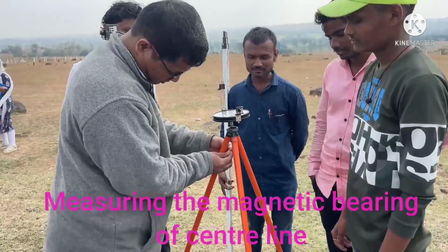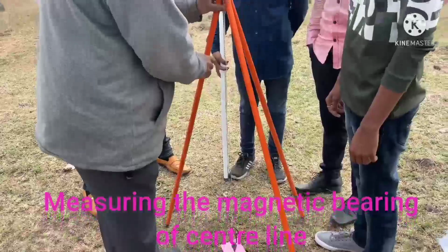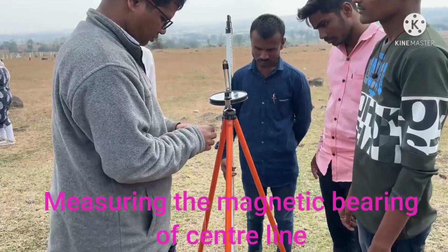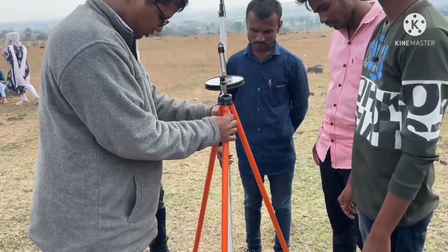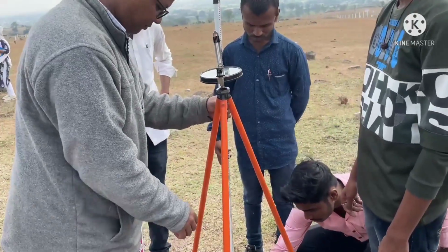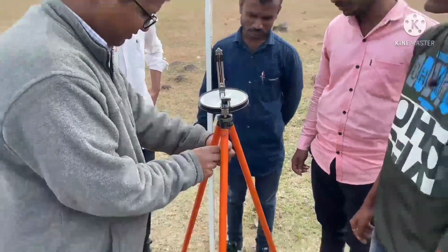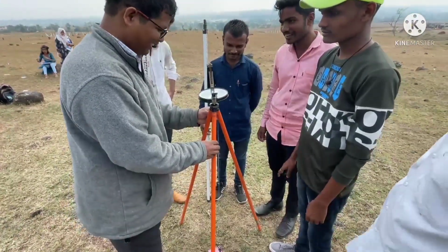Now at the final we are going to measure the magnetic bearing of the center line. That is, we are going to keep the said prismatic compass over the C0 and bisect the ranging rod which has been kept at C100, and measure the magnetic bearing of the said center line. With the help of releasing the plumb bob from the prismatic compass, we are going to check whether it is exactly located over that C0 or not. We are going to adjust it with the help of the tripod legs.